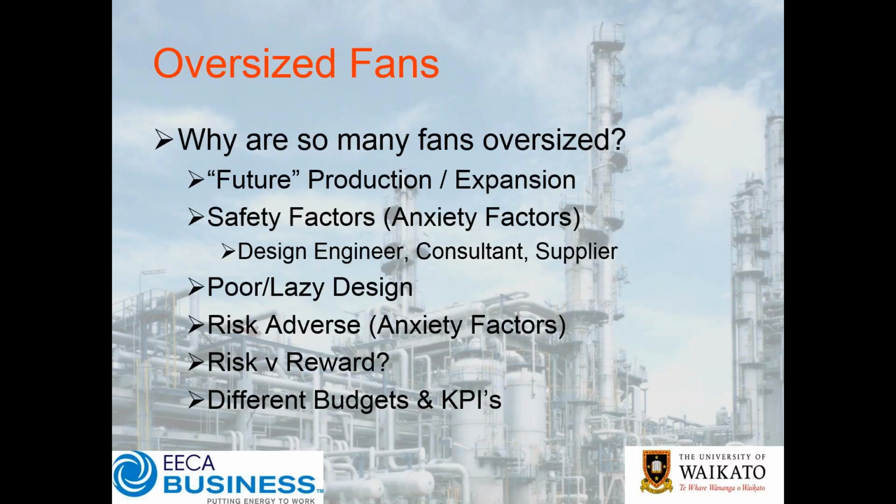We have the safety factors, things that we refer to as the anxiety factor. So we have the design engineer, we'll have a consultant, we'll have a supplier, or multiple people in the supply chain. And if everyone sizing the fan puts their little safety factor or anxiety factor in to make sure that the fan's going to be big enough, that the motor's going to be big enough, very quickly you get a safety factor on top of a safety factor on top of a safety factor.